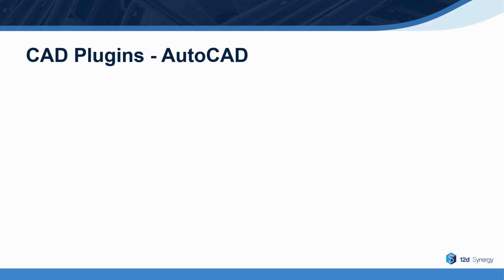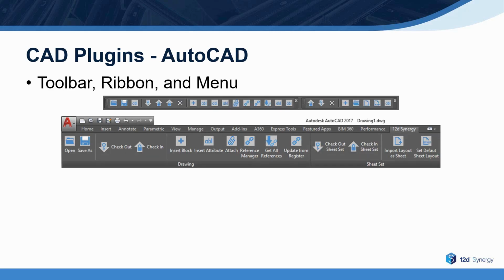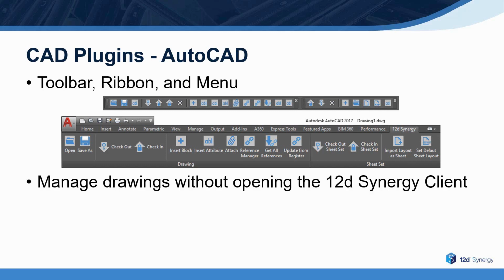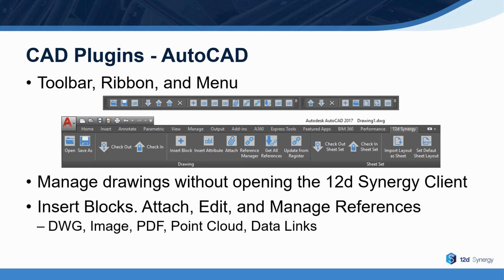When it comes to the CAD plugins for AutoCAD, and I'll show you this as I'll be demonstrating in BricsCAD, this is what the AutoCAD toolbar, ribbon, and menu will look like. Again, 12D Synergy will manage your drawings, and this includes you can open your drawings from CAD without having to open the 12D Synergy client. You can insert your blocks, you can attach and edit and manage your XREFs as well, or references. And these include things like your drawings, images, and PDFs. And of course, it'll manage and update your attributes.